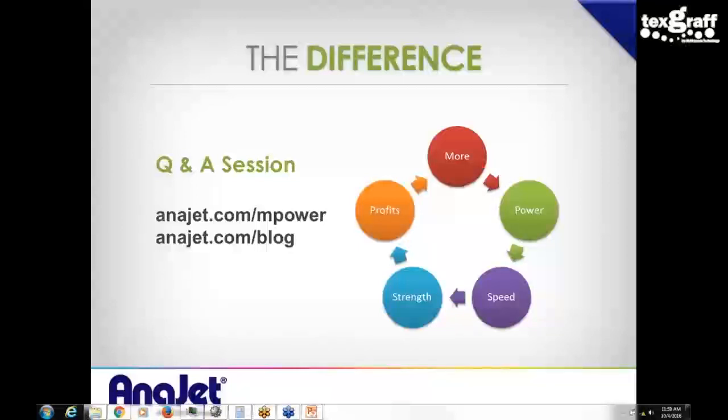The reason is that if a printer sits for a while, there is a regulation of pressure that is always happening inside the printer. Depending on where that regulation of pressure is, it's very likely for the ink to retreat out of the print head and back into the damper system, which is basically a reservoir for the ink. That's totally fine. But when you do a clean, you're not actually wasting as much ink because it's just refiltering that ink out of the damper and back into the print head. So maybe in that particular case, it's only 30 cents worth of ink. That's why I said it's hard to give an exact number.